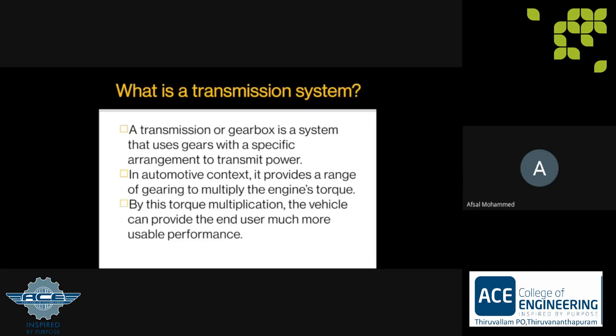And also, there is a factor called torque multiplication. We may not have seen a transmission system in a car or a motorcycle directly, but most of us have definitely been in contact with geared bicycles, right? We can look at that and understand that there are some gear sets. Mostly, if we are looking at a 21 speed bicycle, we can see that there are three sprockets in the front and seven sprockets at the rear. If we shift into first gear, the smallest sprocket in the front and the largest sprocket in the rear will be selected.